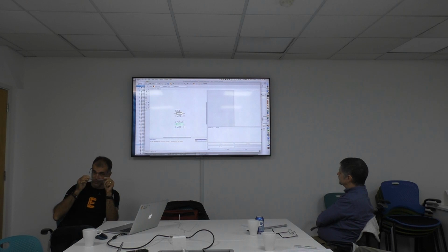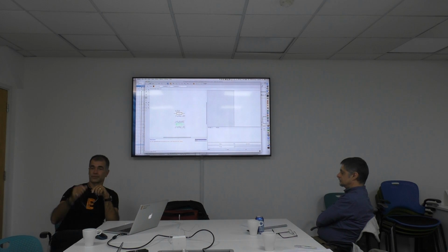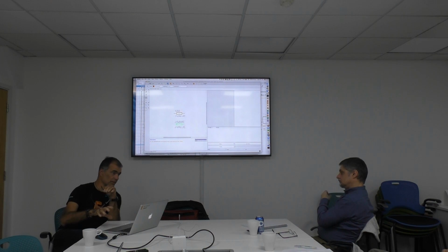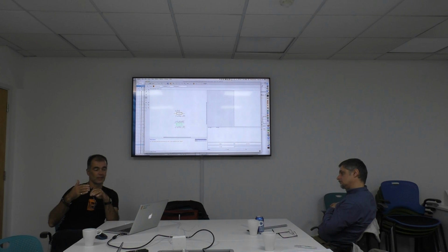There are some devices, think of some gates named AND or OR gates, whatever, where I can have several part symbols. That's then what we call a gate. Or sometimes you see power pins of a component not visible in the schematic or maybe placed somewhere else. So a component can consist of several symbols, which is a gate that we're speaking of. Or think of a connector. You have 96 pins you would like to connect.